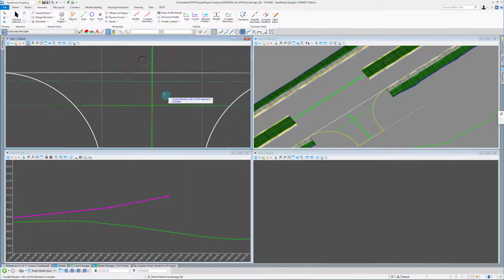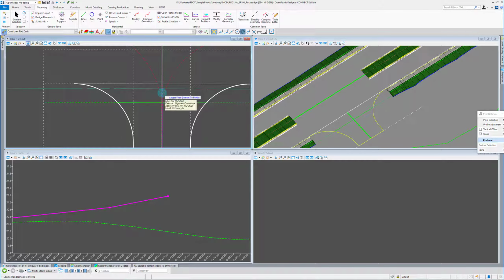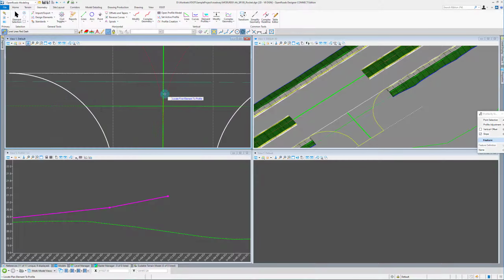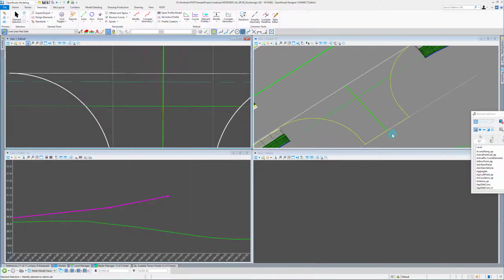and snap here and project our profile. So I'm hitting, see how it's selecting the center line here. I want to select that dash line I just drew. So I'm going to hit tab, and tab should work. Sometimes tab works, sometimes tab doesn't. You can also right click, and that'll get you on that construction line. So now I'm on that construction line. I'm going to reset, and I want to reference this one, slope 0. Now we have our red dashed line on here.